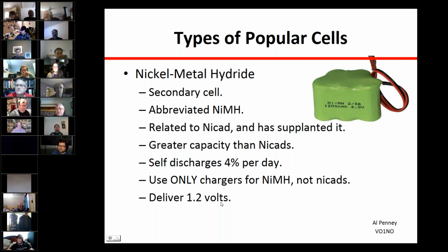The higher cold cranking amps simply means that the battery is bigger and can provide more current over a short period. That would be related to internal resistance, but it's because it's a bigger battery. Wade, a float charge is just a low level current that's applied to it at all times, such as if you left it in a charger, it would just be a low level current that keeps the charge topped up. Trickle charge, yeah.